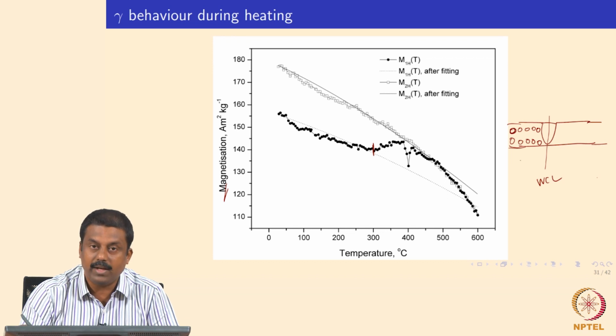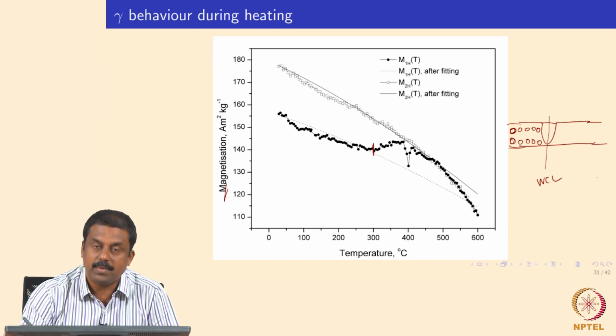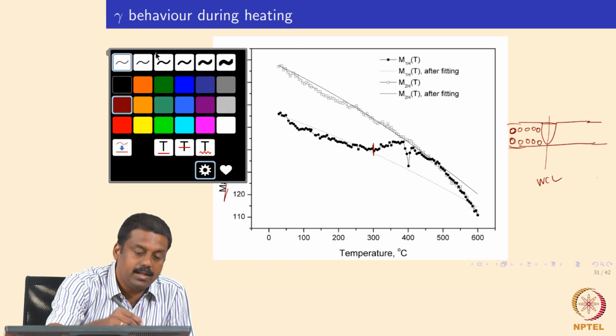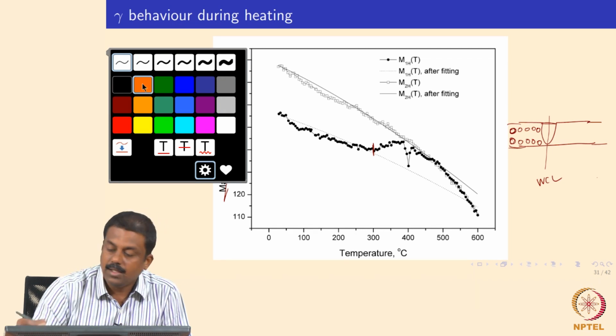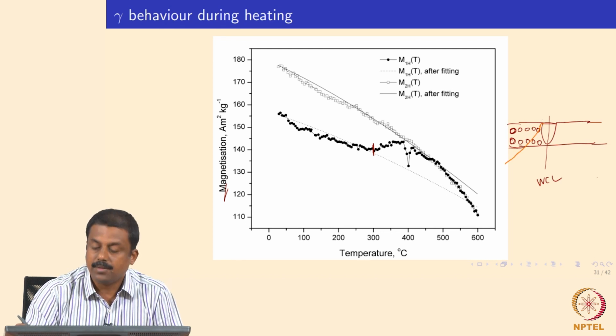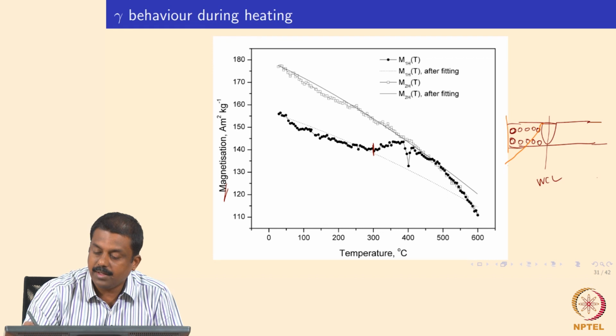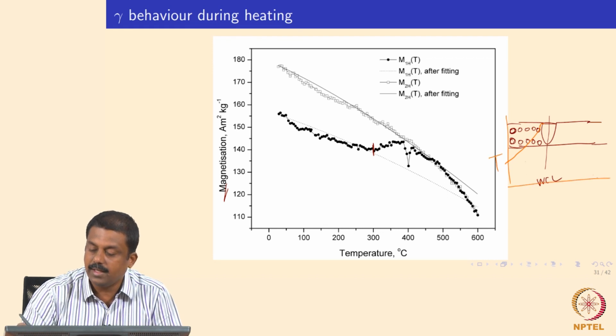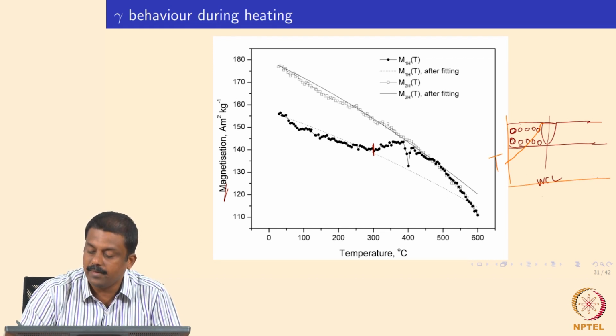For example, in this drawing, I have drawn circles where we machine the samples out and then do the magnetic saturation measurement. Suppose this is your thermal profile after welding, and the temperature is decreasing as a function of distance from the weld center line.